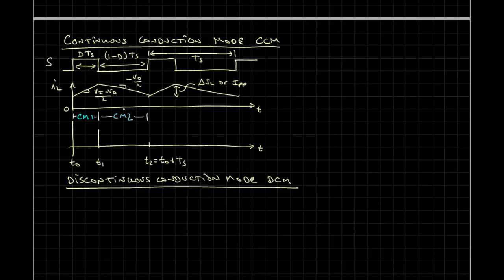When the switch is off, it's going to be Vin. And if we draw the diode voltage, the diode voltage will be equal to Vin when the switch is on. This is going to be V diode. So they just complement each other. The maximum voltage stress on these devices, the switch, the transistor and the diode, is going to be ideally just Vin.